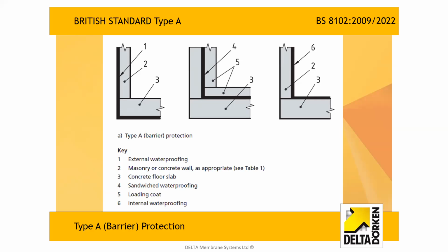So it was basically a sheet membrane which was applied to the inside of the structure and stuck on, and then backfilled, with an internal wall and maybe a reinforced concrete slab on the inside, which sandwiched the waterproofing. That's now gone because it was a bad idea to start with, because it was pushed off when water came through the structure inevitably. Inconvenient things like wall ties were conveniently not thought about with sandwich waterproofing, because